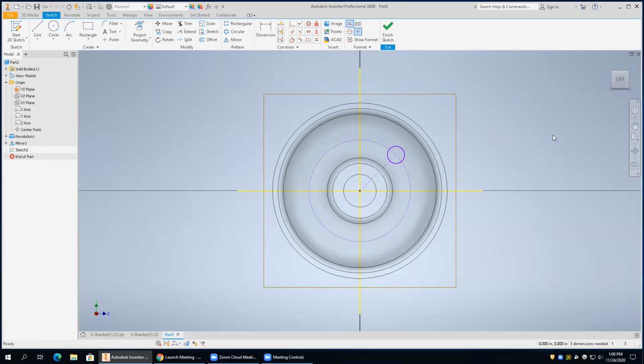So I'm going to now place a dimension from that axis line to that construction line, pull it out here. Whatever the dimension says it is, I want to make it 30 degrees, okay? We want to make it 30 degrees. We're going to dimension this construction line circle.